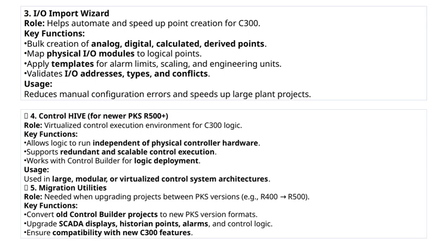It also maps physical I/O modules to logical points, applies templates for alarm limits, scaling, and engineering units, and validates I/O addresses, types, and conflicts. This tool reduces manual configuration errors and speeds up large plant projects, making the entire process more efficient and reliable.